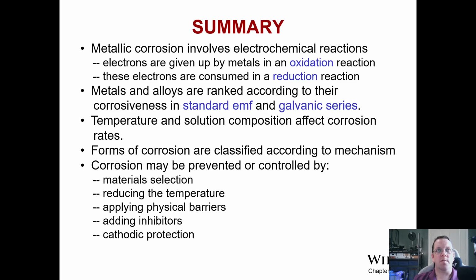So these metals are ranked based on both the galvanic series and then the standard electromotive force. So it gives us an idea how likely they are to react, how extremely they react, how much electromotive force there is between them. So there's a large difference between the things at the two ends of the EMF spectrum. And so if you put those two together, the higher the difference between them, the higher that standard potential difference is, the more aggressively they're going to corrode, and the more quickly they're going to create a galvanic path.